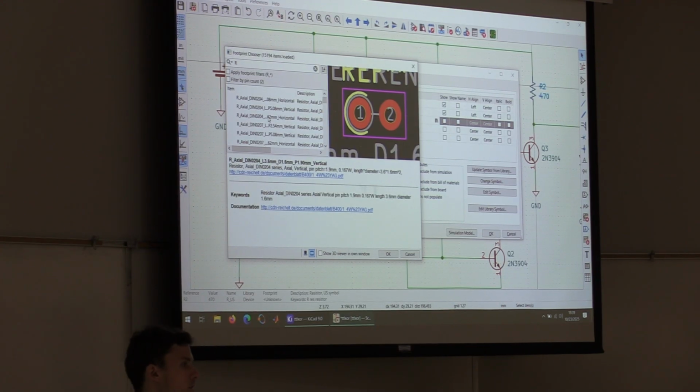Usually you'd select a footprint. These components might have a lot of different footprints. You'd select it based on your size requirements. So sometimes it's better to have, say, those axial resistors stick up and then have a lead bend over and sort of have it vertical versus horizontal where it's a lot longer.